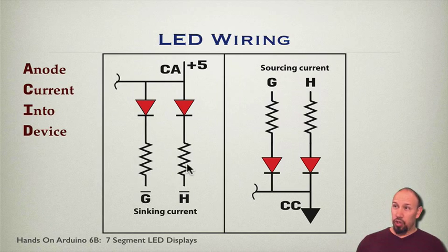A resistor is generally needed. You would think that since they're making a package out of this and they always need a resistance in there, they would go ahead and put resistors in the package, but they don't. So you have to supply your own resistors, but that's probably fine because different people might want brighter or lighter, or they may want to switch in one resistor or another in order to dim the lights. Whoever works with these devices has to supply their own resistors.